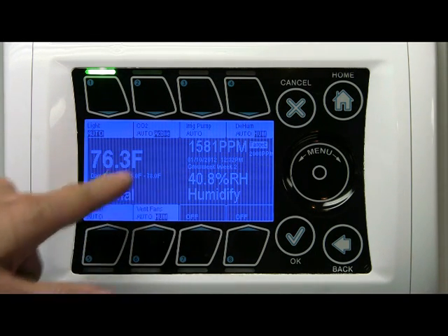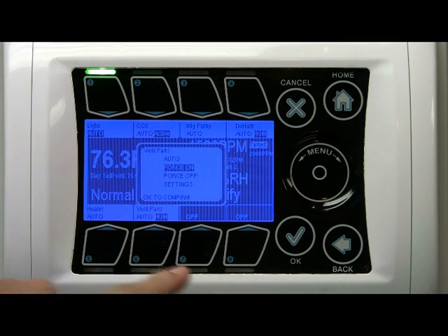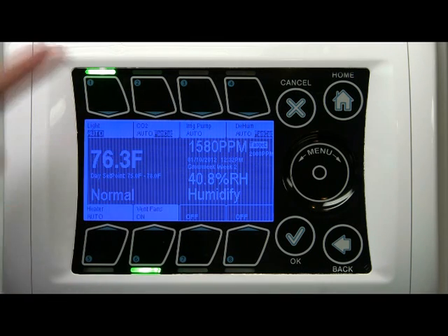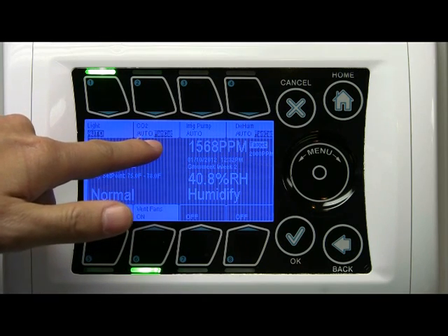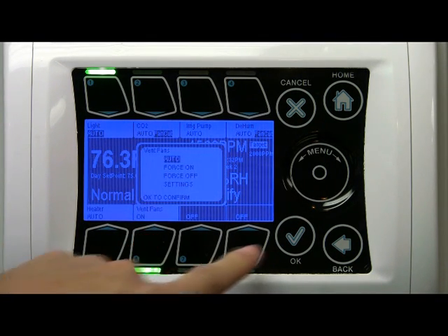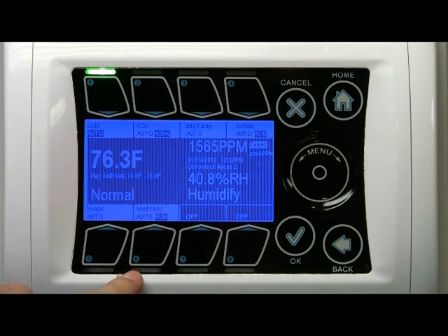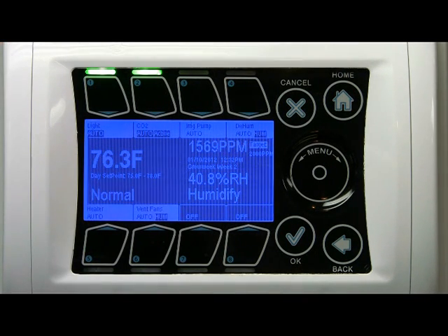Same way, we have a ventilation fan here. Let's say I'm going to simulate the fan on by forcing it on. Now you're exchanging air with outside. You can see that the CO2 is off now. It's saying fan cut. If I go to auto, which in this mode here the vent fan is off, then the CO2 is now once again active. So that's how the iPonic 600 controls the CO2 devices.